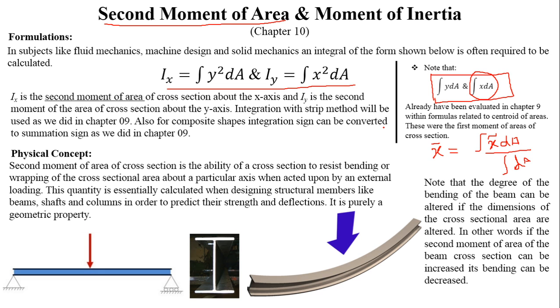First moment of area are integrals of this type, integral x dA or integral y dA, and they are used in calculation of centroid, for areas and volumes.